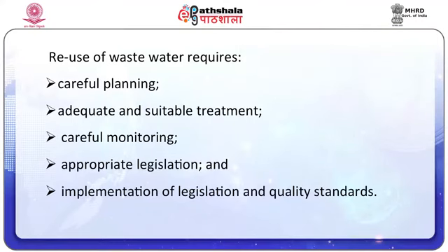Reuse of wastewater requires careful planning, adequate and suitable treatment, careful monitoring, appropriate legislation, and implementation of legislation and quality standards. The quality of the once used water and the specific type of reuse define the levels of subsequent treatment needed as well as the associated treatment costs.